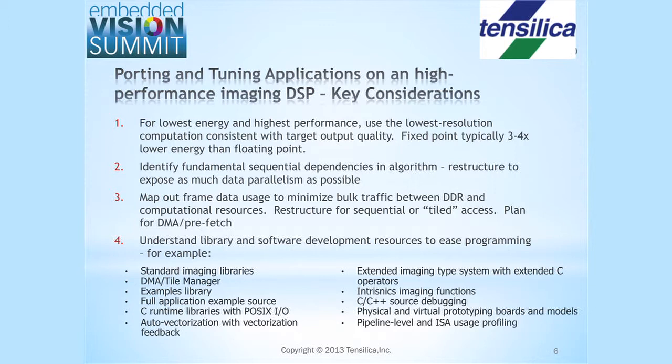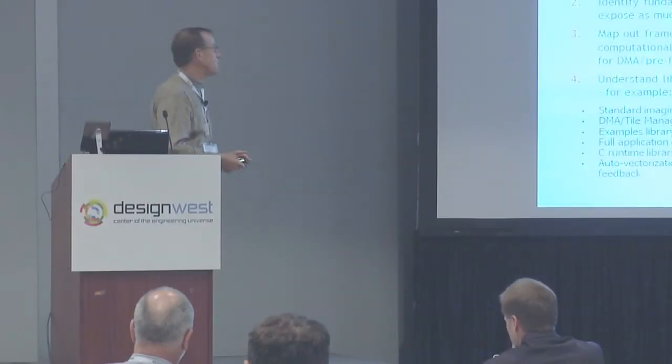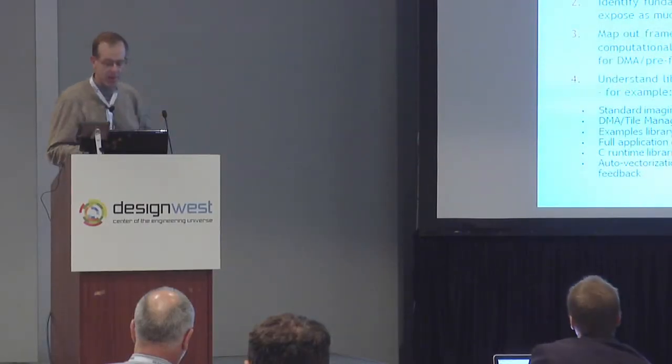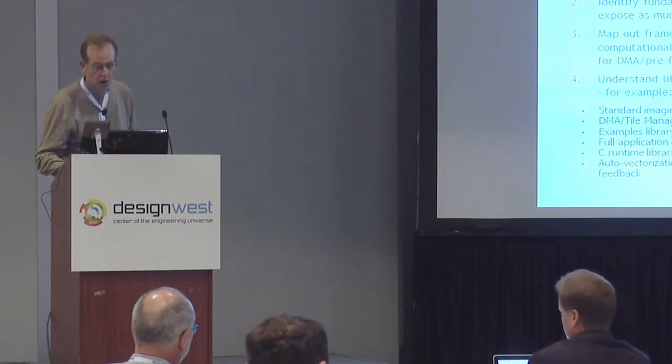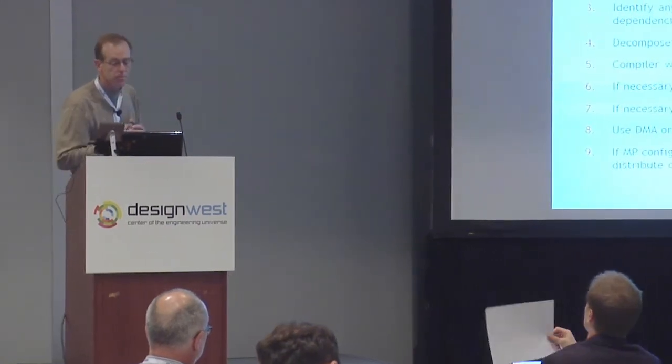And finally, as you launch into the overall porting exercise, it's important to understand what kind of library resources you have available, because typically you'll have the ability to run OpenCV, but you'll also have a range of more optimized platform-specific libraries that keep you from having to reinvent the wheel. And all of these other things that allow you to run large-scale applications in your simulation environment or in your FPGA environment are going to be key. And I've listed a whole bunch of things there that are useful and you should look for.